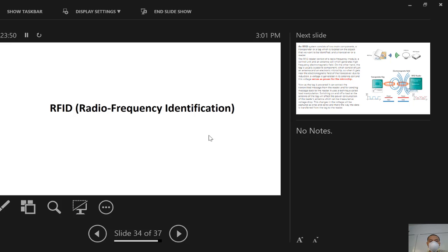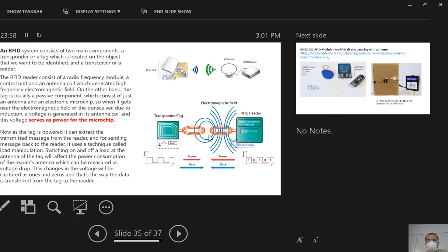So RFID is everywhere in the real world. You have your little Sky card. It has RFID inside. So how does that work? It has an integrated circuit chip inside, and also it has a coil. That coil will receive the radiation from the reader, and the reader not only sends a signal to it, but also accepts a signal from it, and also powers it up. Is that amazing? So definitely, you should know that there's no battery in your card. Right? Common sense.